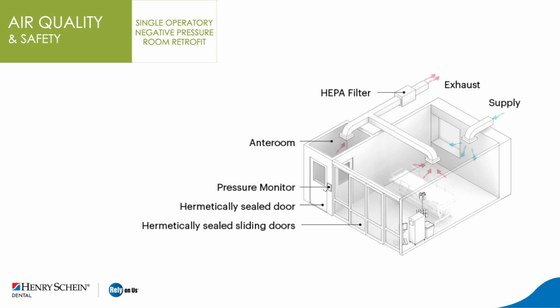Operating rooms have a room air exchange rate ranging from 20 to 30 times an hour. And right now, what I've heard is that OSHA is considering mandating an air exchange rate of 6 times per hour in most commercial facilities.